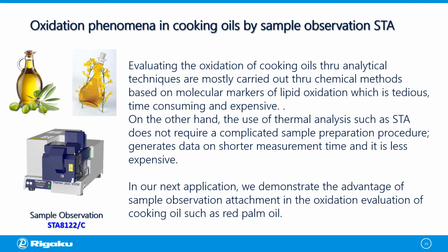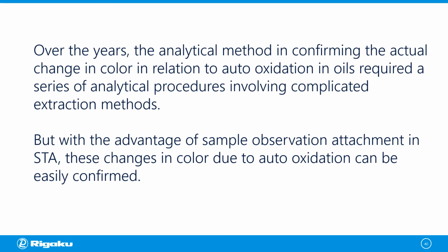In our next application, we demonstrate the advantage of STA equipped with a sample observation attachment in the oxidation evaluation of cooking oil, such as red palm oil. Over the years, the analytical method for confirming the actual change in color in relation to auto-oxidation in oils required a series of analytical procedures involving complicated extraction methods. But with the advantage of the sample observation attachment in STA, these changes in color due to oxidation can be easily confirmed.